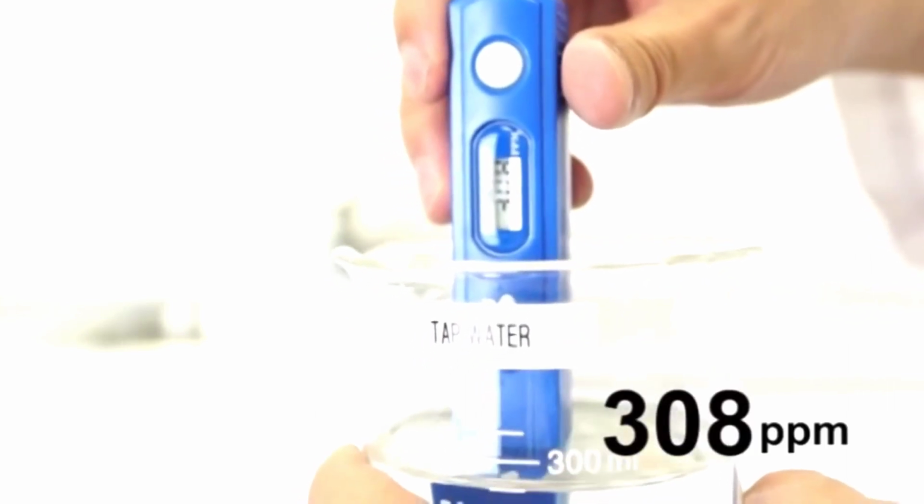Now that both of the readings are done, we can calculate the percentage of contaminant removal of the reverse osmosis. The rejection rate can be found by subtracting the reverse osmosis TDS from the tap water TDS and dividing by the tap water TDS. A good reverse osmosis system should remove 90 to 99% of the contaminants of the water. Here's an example.